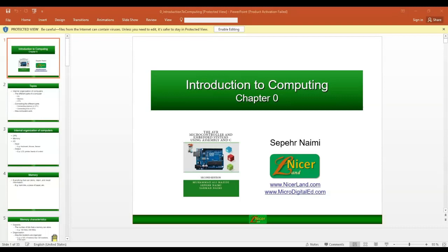Here is the block diagram of a memory. It has these data lines. These are the address lines. This is the write enable. As the bar is placed here, it is active low, like when we give a zero signal to it, it performs its functionality. Here we have output enable, and this is chip select. Chip select just means selecting this chip for its working.